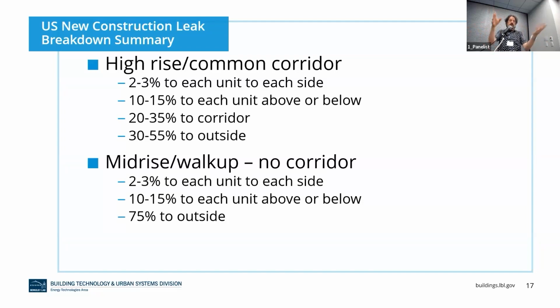If you have a corridor, you tend to leak to it, probably because that's where the door is. And certainly in some HVAC systems, we are deliberately supplying air via the corridor as a supply air system. So you have a question about, well, the door leaked, but it's supposed to leak. And I don't know how we deal with that from a construction quality point of view.